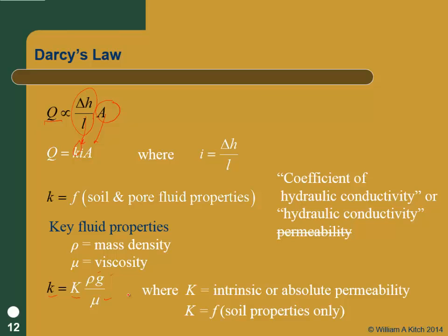I'm careful to do that, but you'll find it in lots of previous writings, particularly some of the papers I'm going to actually read, because some of them are several decades old. You'll see it referred to as a permeability. So just make sure you understand the difference between the intrinsic permeability and the hydraulic conductivity. Ours includes all those things. So if you're doing geoenvironmental work and you're trying to pump gasoline out of the ground that came from a leaking storage tank, you're going to have to deal with the fact that the stuff you're trying to move through the soil is not water. But most of the time we're dealing with water.